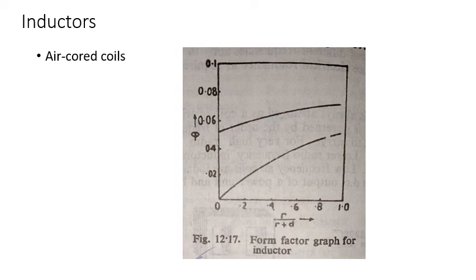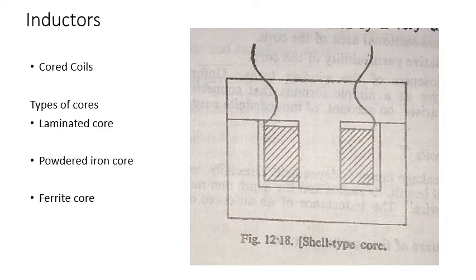Now the core coils. In high frequency ranges, coil formers may be of a ceramic material and have no core. But receiver coils in the lower region of the high frequency band use cores of high permeability material, classed as ferrite.